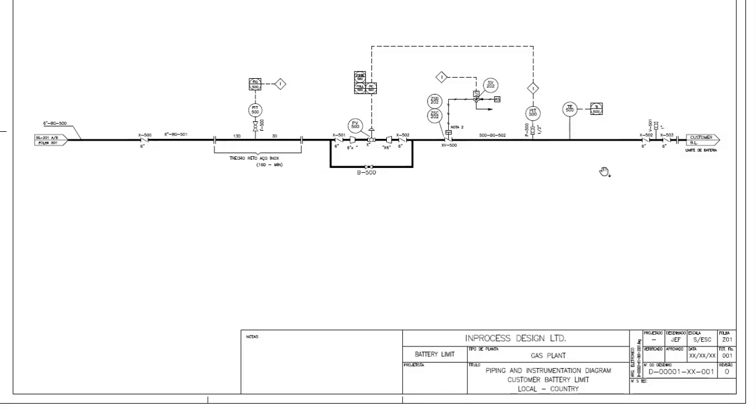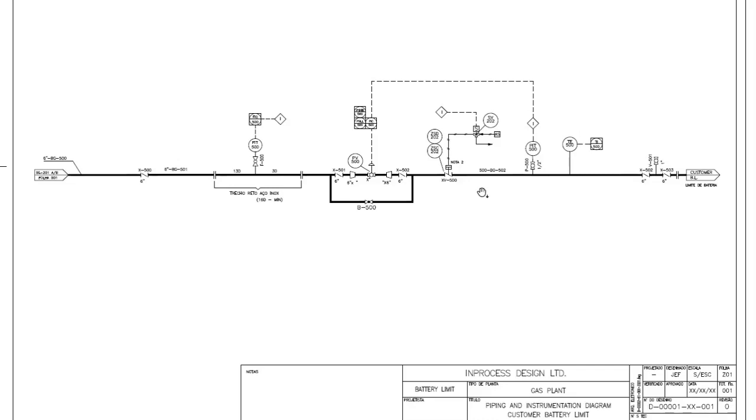And in most companies, or in many companies, there is also a manual valve list to make it easier for the operator to identify a manual valve in the field. I didn't show you a manual valve list, but it's very similar to a line list and an instrumentation list. The main purpose is to make it easier to identify a valve, see if there is a number available for it, and see in which P&ID sheet you can find it.